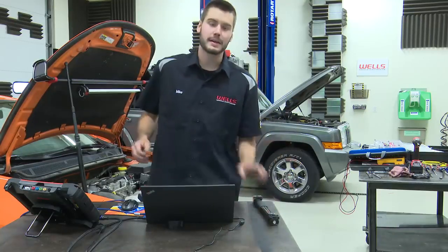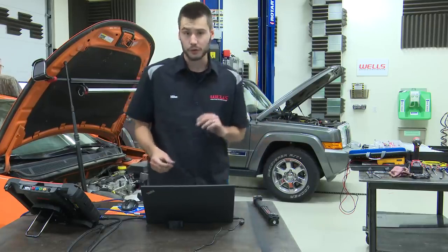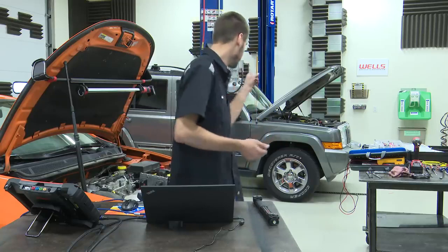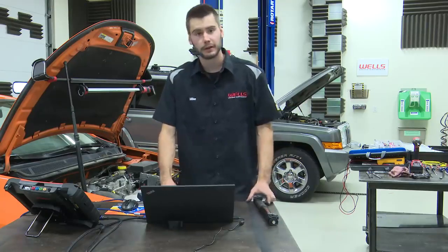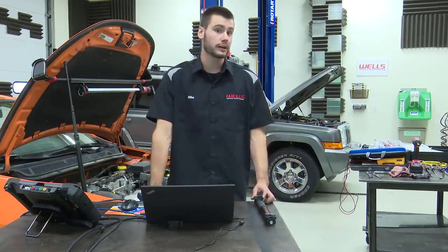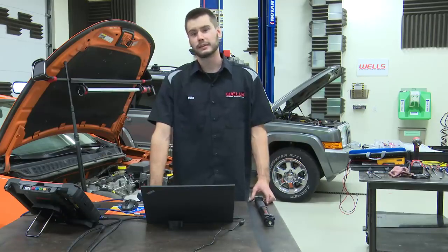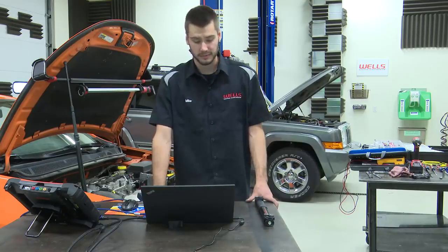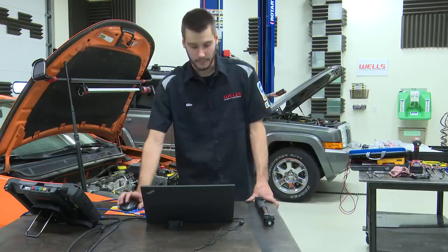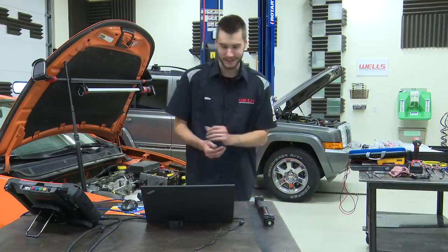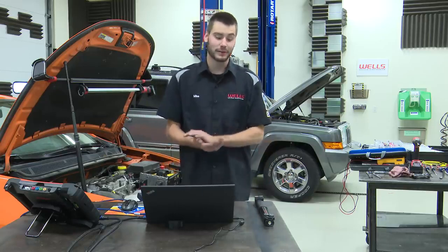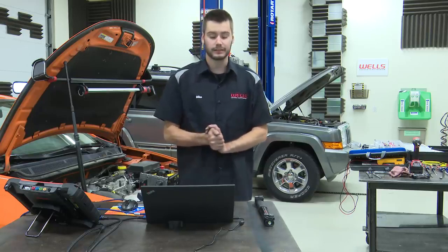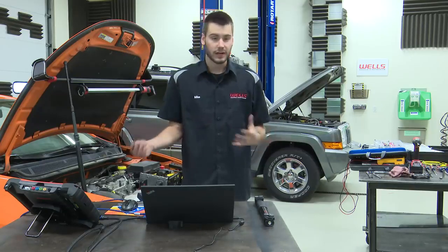The Jeep originally came in with a P0124 throttle position code. This is a 4.7 liter in this thing, so it's the old school 3-wire throttle position, drive by cable, not drive by wire. This thing came in, it was kind of hesitating, the idle was kind of stumbling. She said it stalled out 1 or 2 times. So we took a peek at it, and it does not need a TIPM module, totally integrated power module. It does not. This one just ended up being a bad throttle position sensor, and I'm going to say that right away because there's a couple different ways to get there.